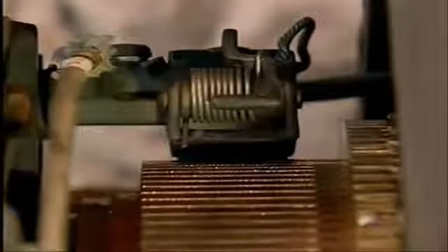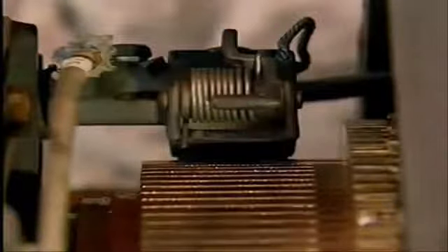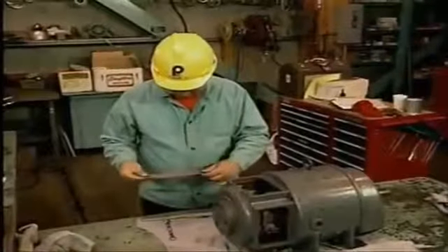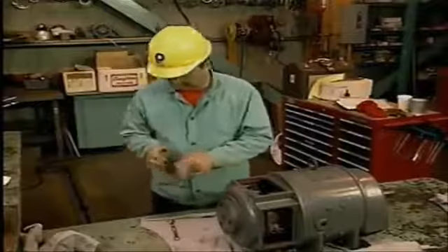Your facility may have specific procedures for you to follow when you're seating new brushes in their rigging. If no procedures are specified, there are several that can be used. For example, one way is to seat brushes using extra fine flint paper to alter the shape of the brush. When this method is used, a strip of flint paper is torn off that is at least as wide as the brush.